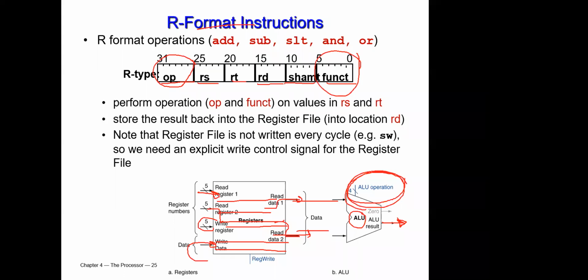Let's say I have the output here as results, and let's say that I have already done the addition. So now I have the addition results. What do I need to do afterward? Basically, I need to dump that particular data to a certain location defined by the destination register. From the destination register's 5-bit address, I already know, as an example, that I have to dump it in this particular location.